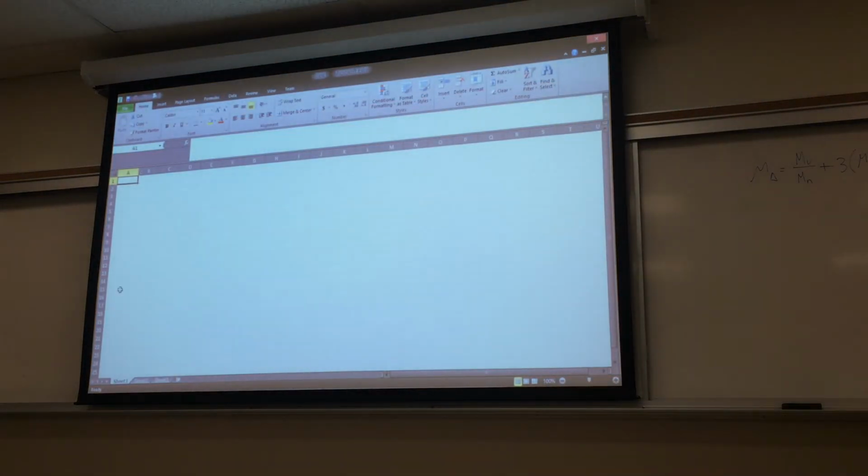Let's say I want a moment of inertia of 24 feet to the 4th. That's what was given. I can come up with an equivalent circular section, based on the fact that the moment of inertia for a circle is pi over 64 times diameter to the 4th. So I can back solve in this case.